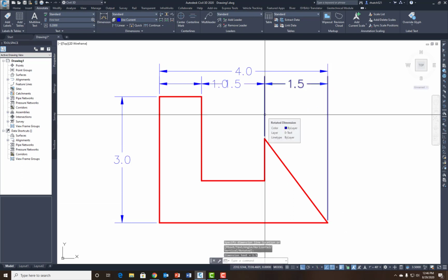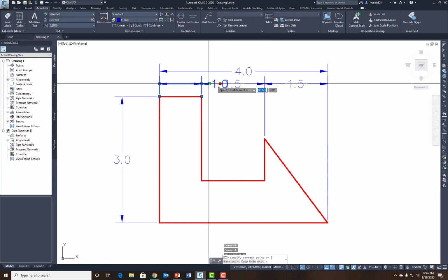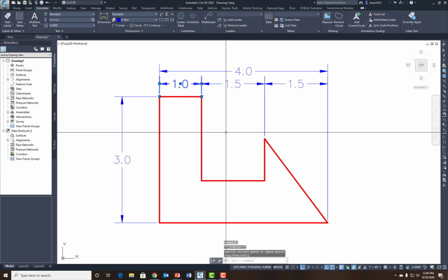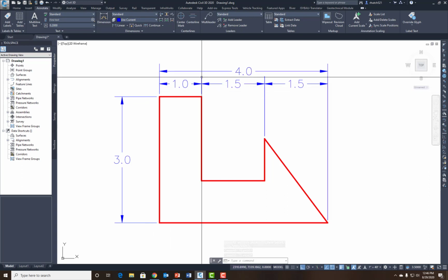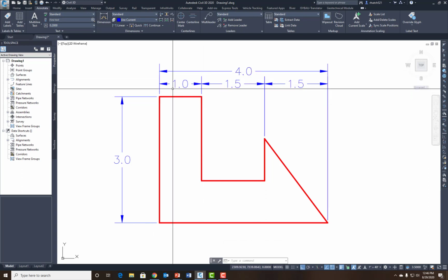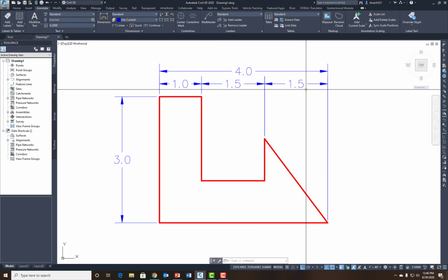But a couple things you'll notice. First off, I have this little cluster right here going on. And so normally I might want to change it, something like that. So now it's still clear. We can see all the things. We don't have anything crossing itself right here. So I don't have a cross here or here, here. This extension line comes up, but there's no dimension lines that are crossing each other.